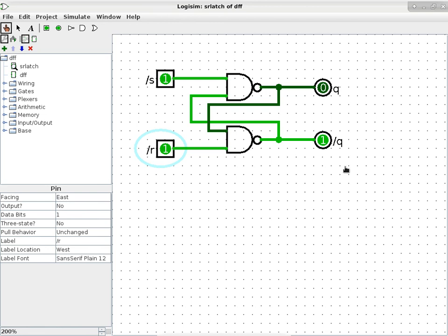Okay, so what changed? We couldn't figure out anything that got changed. The firmware was not changed. Software was not changed. When we looked at all the components, nothing was changed. And then somebody noticed the date stamp on the chips changed. Let's say we went from October 2016 to December 2017, something along that line. All the chips have a date code on it. We noticed that the problem only shows up on boards that have a chip of the newer date code. All the ones with the older date code were not affected. So we go, okay, that's really odd.